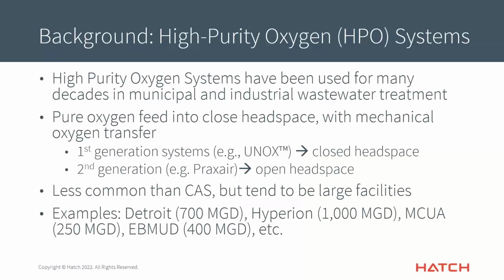But generally, the idea is that you have some sort of headspace, and then you fill that with this high purity oxygen feed, and then you get that oxygen transfer into the liquid at a very, very high rate, much more so than you would get with air. And then that allows for very high rates of growth from your biomass because oxygen is not going to be limiting in your system the way that it would be in other situations. So there was sort of a first generation of these ideas.